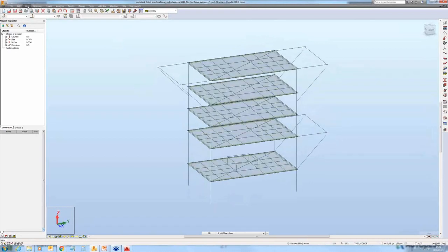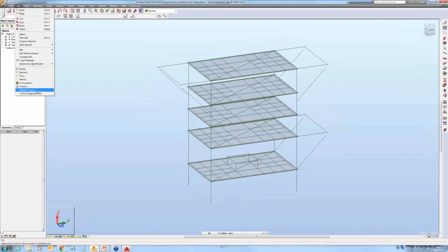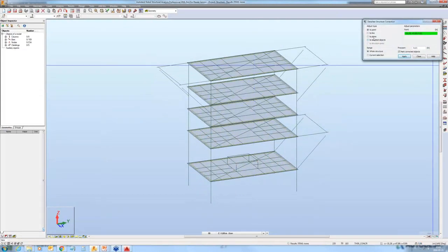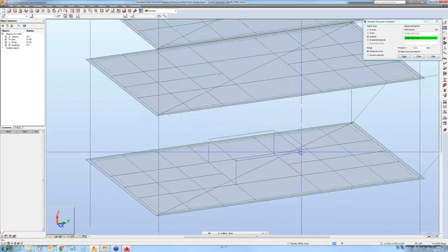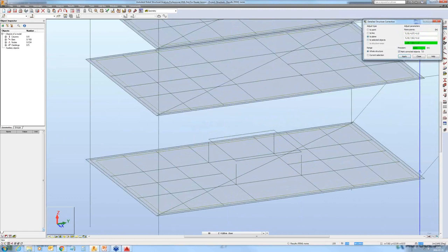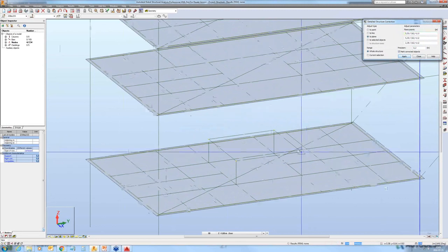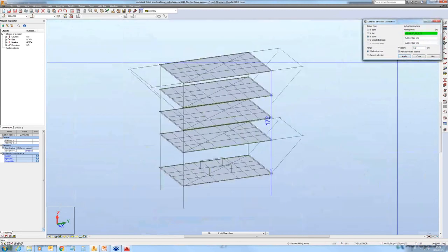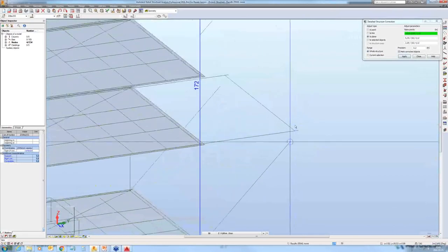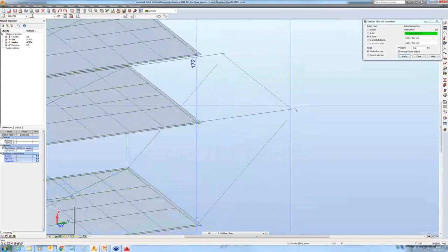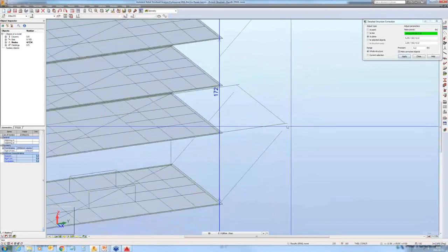So this time, I'm going to use the detailed correct option, and I will indicate the plane. So here we have some gaps between this plane and these short columns. I will specify the distance that matches the gap, and if I press the apply button, you can see that these elements are connected. I'm going to work in a similar way to get rid of these short cantilevers and connect the struts with the platforms.